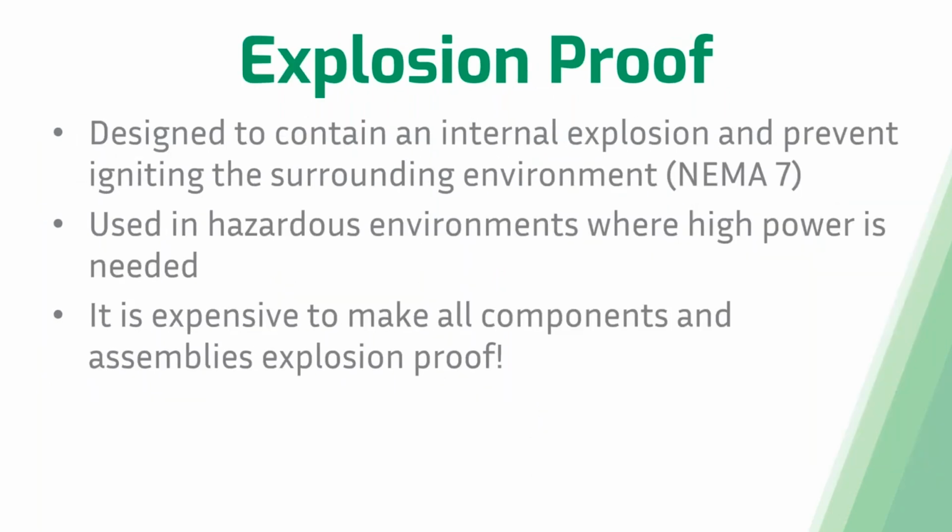Instead, you're going to see explosion-proof pumps. These are designed to contain an internal explosion and prevent igniting the surrounding environment. This falls under the NEMA 7 classification. So this is going to be used in hazardous environments where high power is needed, which you need high power to operate a pump.